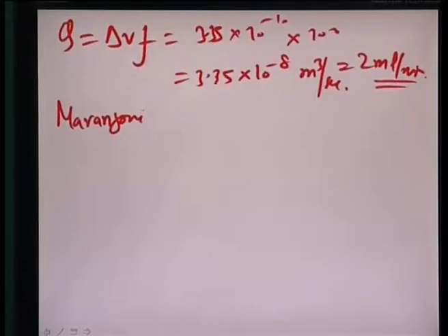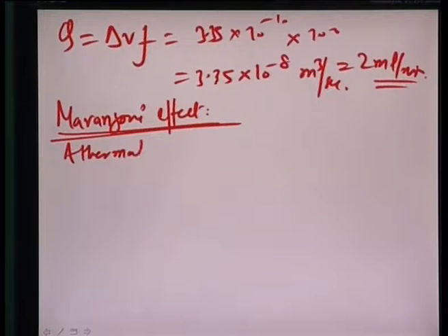So, let us do an example where we talk about how we can determine the driving force on a bubble, given the surface tensions of the water-air interface at different temperatures at which the bubble is heated. Let us do this example on the Marangoni effect. So, we have a thermal bubble which is created in a capillary.